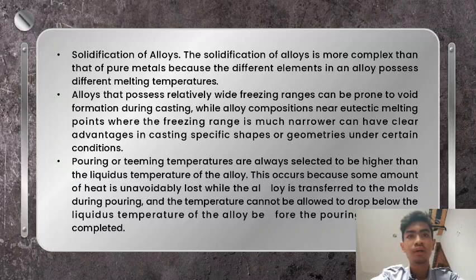Different alloy compositions have different liquidus and solidus temperatures, and the lines that appear on a binary phase diagram that separate these regions from each other are referred to as liquidus lines and solidus lines. Respectively, when some of the liquid metal begins to solidify, the technical term for this event is freezing. Freezing continues until solidification is complete.